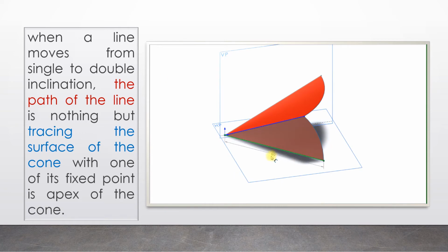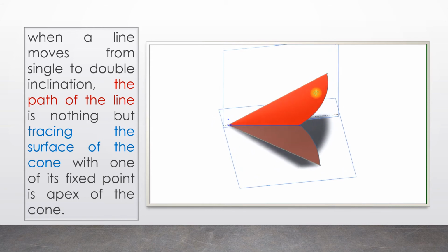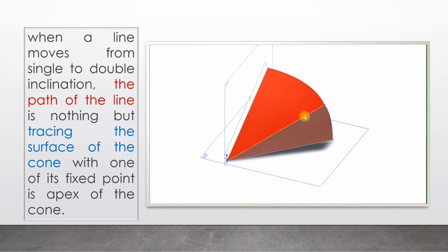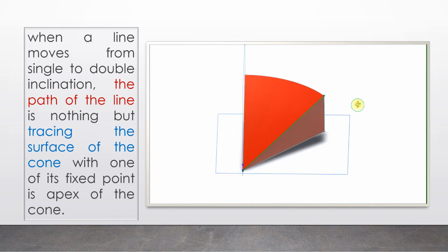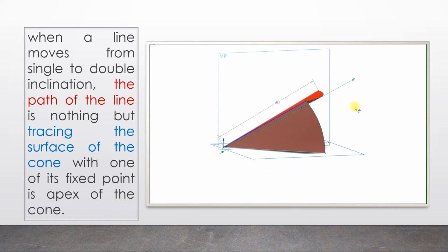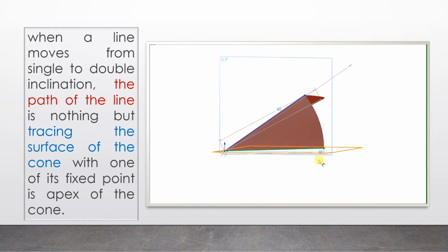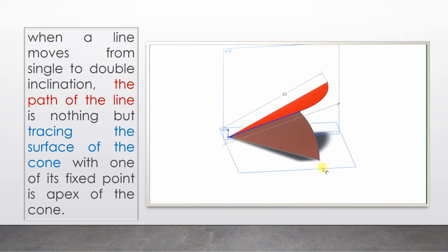B1 to B3 or B2 to B3 will be the same, and you can understand by seeing the dimensions of the cone. That is, the actual or true length is visible in the front view and visible in the top view for a line which is parallel to XY, but even AB3 also has the same length, because these are lines in space made inclined. But in orthographic projection, because of the convention followed, it looks as if it is shortened.